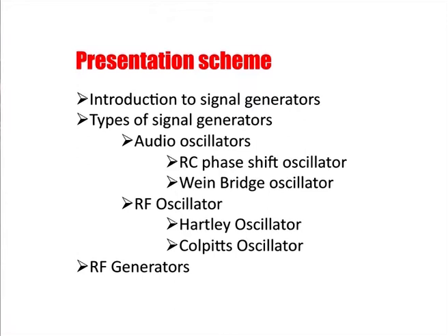Well, coming on to oscillators, oscillators are capable of generating oscillations in the form of electrical signals. Basically, all oscillators generate sinusoidal waves. As far as the principle of oscillators is concerned, it is basically the Barkhausen criteria, which we will discuss here. Oscillators are basically feedback circuits in which some fraction of the output of an amplifier is again fed back and mixed to the input.